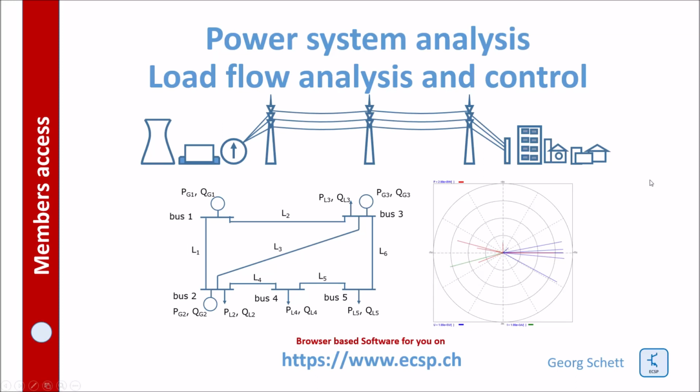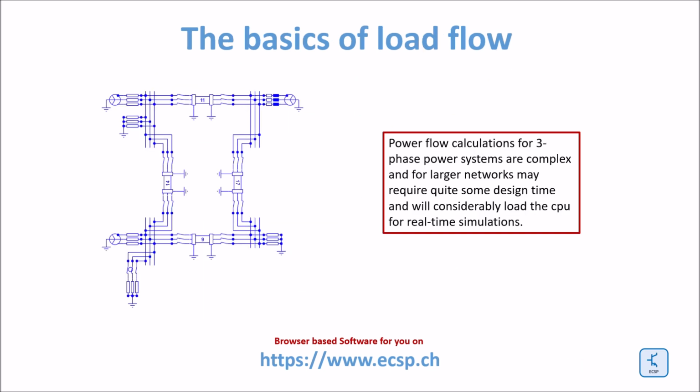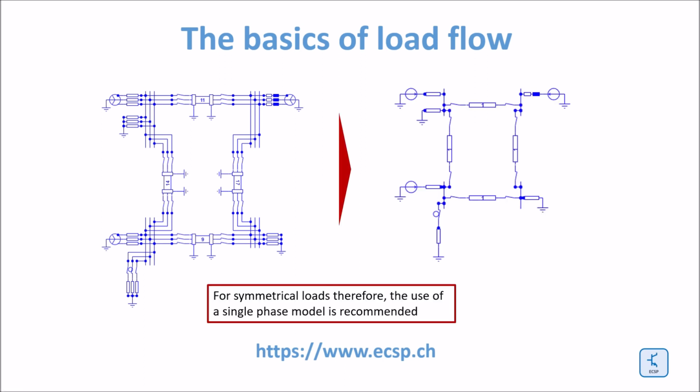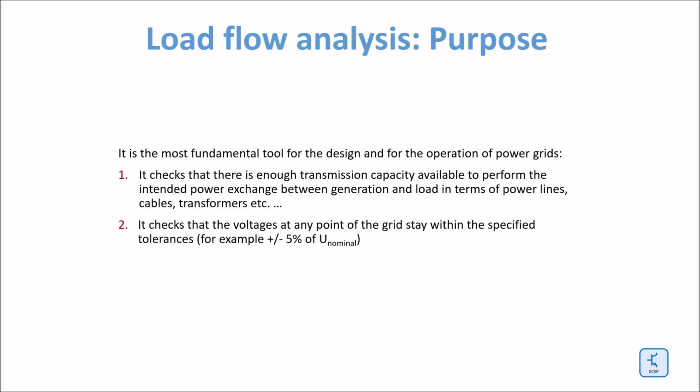Hello, today I want to show you how power system analysis and load flow analysis is performed. This will be the toughest lecture I ever had. Power grids are three-phase systems which are complex to calculate and thus require a lot of CPU time. For load flow calculations, however, we can assume that the loads are symmetrical and therefore we can use a single-phase model. Load flow analysis is one of the most fundamental tools for the design and the operation of power grids.